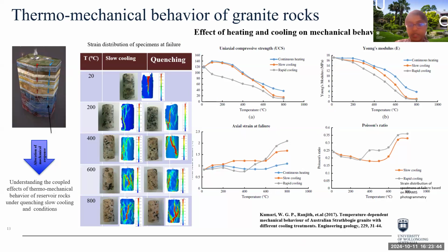Researchers have observed a significant increment in thermal-induced crack density generally after 600 degrees. The main reason for this is suggested as the alpha to beta transition of quartz, which occurs at 573 degrees. Here, they considered a specific granite called Strathbogie granite, which consists of a large amount of quartz, about 50% of its mass, which is the primary constituent of this thermally induced damage.